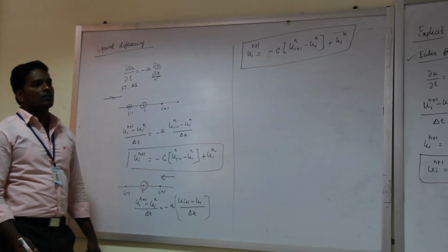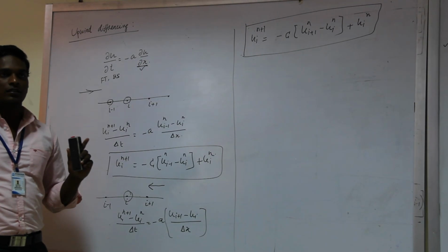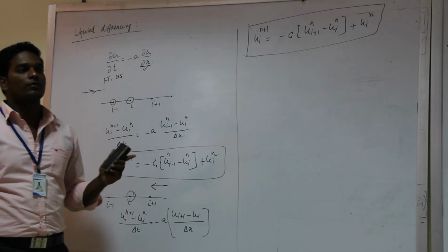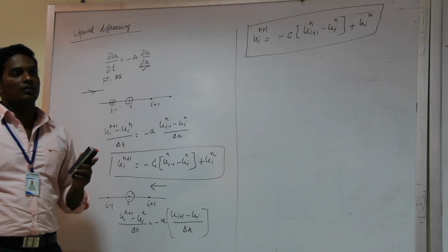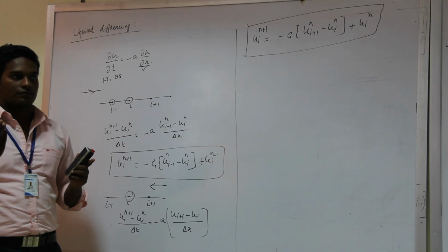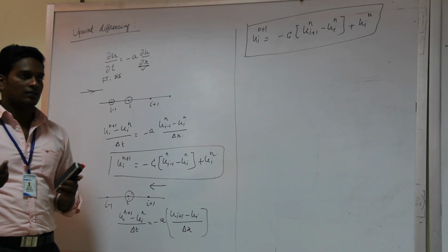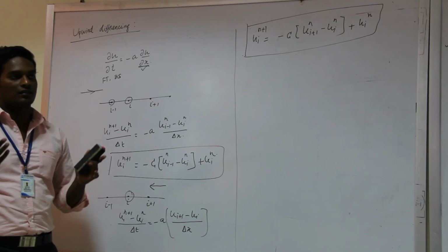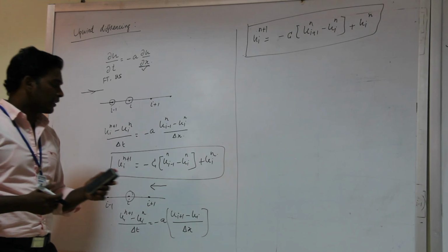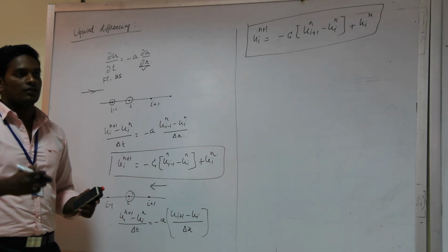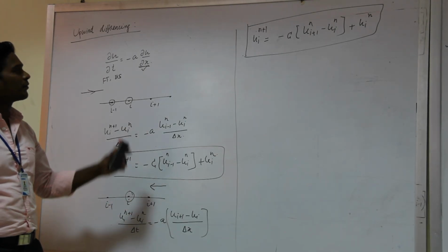Like when you do your elliptic equation, 100 degree centigrade, 0 degree centigrade, in between you have to guess the temperature. What's a preferable guess value for the temperature at an intermediate node? It's within 0 to 100. So for a node neighboring 100, what's a general guess? 30 or 40. As time keeps going on, or space keeps going on, it interpolates the value and finally reaches a steady state. So like that you have to guess which direction the disturbance takes place from. You can choose that node as your preference node. Okay. So this is the general technique behind the upwind difference scheme.